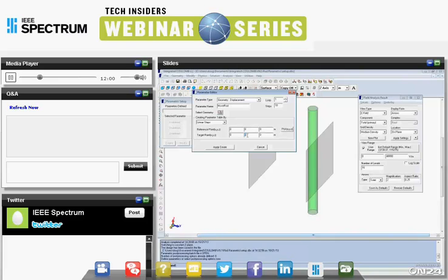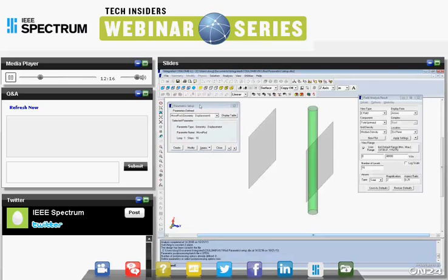And what I'm going to do is move it to the left, and that's the negative y direction as seen here, by a distance of minus 0.3. So I click apply and I see a parameter created, and so long as this parameter is selected, I see the rod showing up as green. Now if I want to visually confirm what I've just set up, I can go to a validation routine and click OK, and I see there's the various positions that are going to be studied. So that looks good to me.